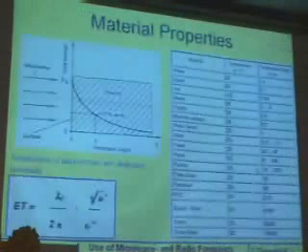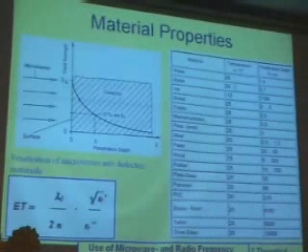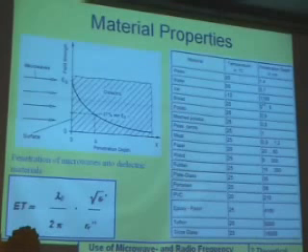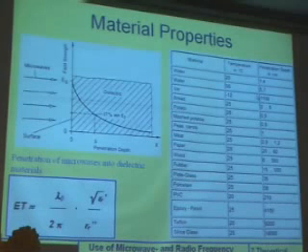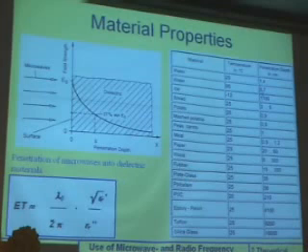These are the penetration depths for microwaves, and you see when we have ice, for example, ice is not absorbing microwave energy as I described before, and therefore we have high penetration depths into ice. But if the ice is melting, if the dipole character is able to move the dipoles in the electric field, the electric energy is absorbed, attenuated in the product, and the penetration depth goes down. This is very important to keep this in mind, otherwise you cannot